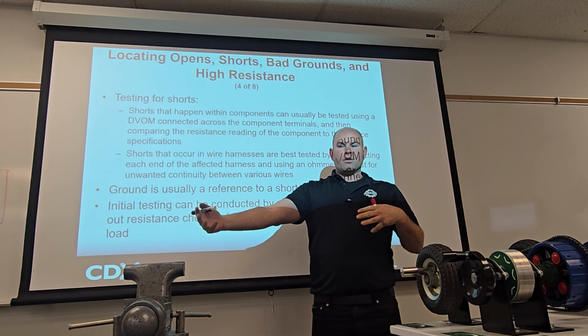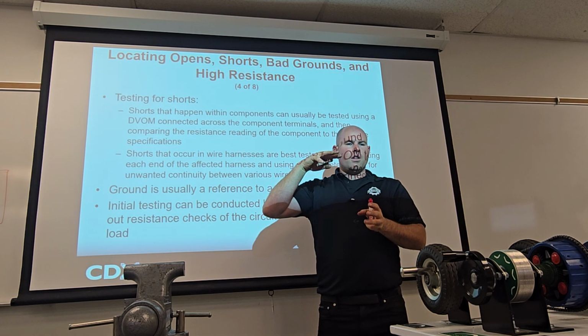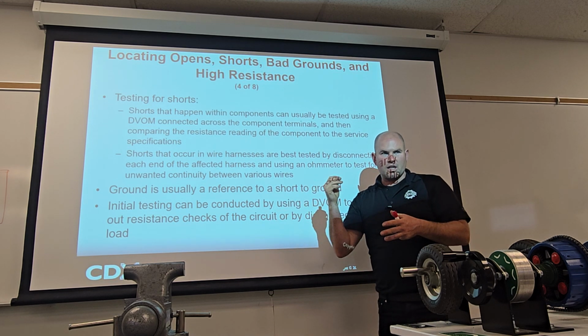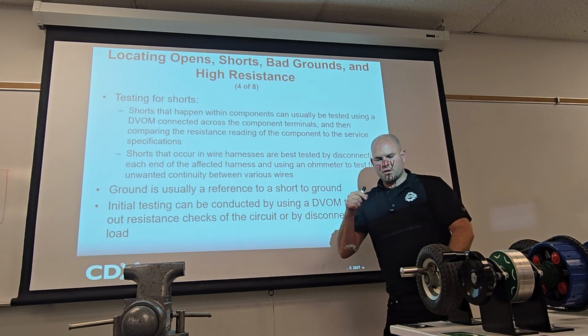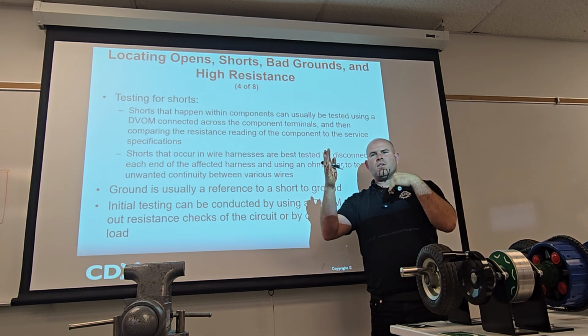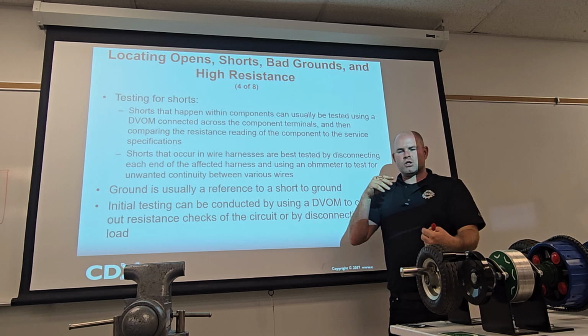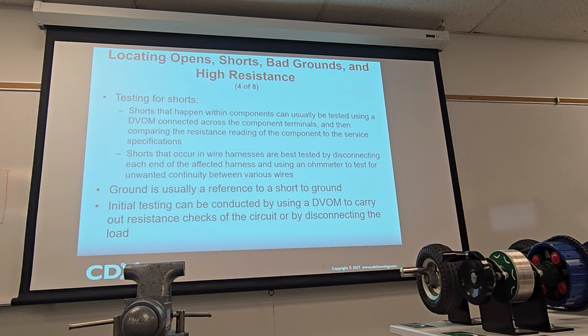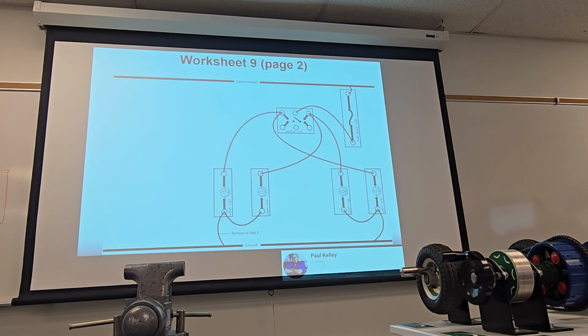That provides the resistance the circuit needs to not blow the fuse, plus the fuse is out anyway. Then you would literally just disconnect components one at a time until the headlight went out. And that would be, let's say it's shorted to ground. If you plugged a bulb into the fuse, that should not light the bulb.